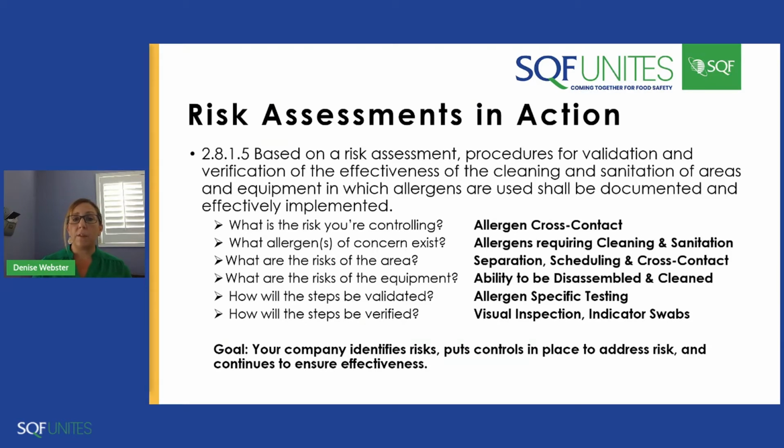Do we have one type of allergen throughout the facility, so cross-contact just doesn't exist? Or we might have wheat that is in all of our bread, but we have one or two SKUs that have soy. Well, we then need to develop a risk assessment and a plan to address the validation and verification activities specifically for cleaning those areas. We also have to address separation and scheduling further to control that potential for cross-contact.